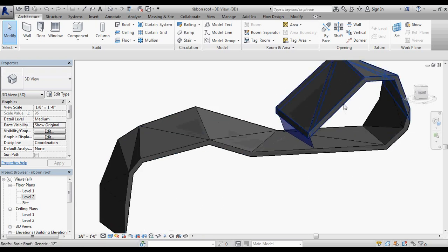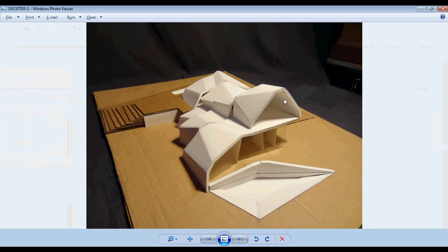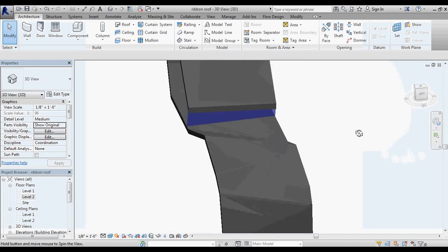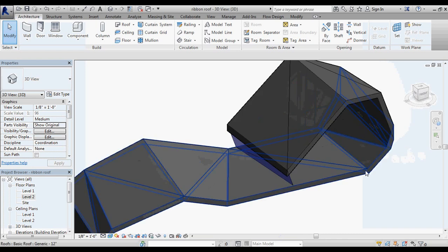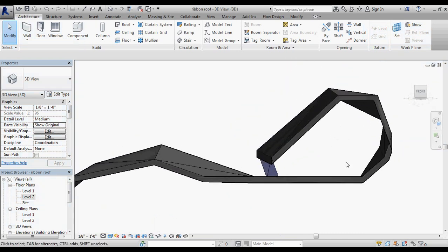So what I do want to do is, one of the reasons why I built these as separate roofs is, if you notice in this model, this actually cuts back at some point and lands further back on the roof. And two reasons why that's divided up into two pieces. The first is definitely wanted to be able to allow Revit to resolve coming up and then coming over.